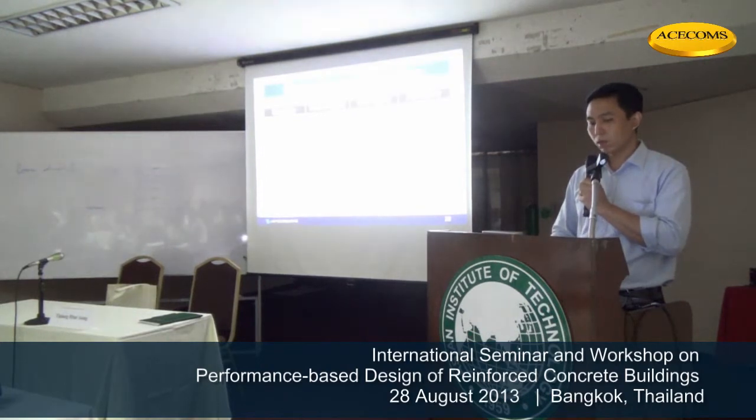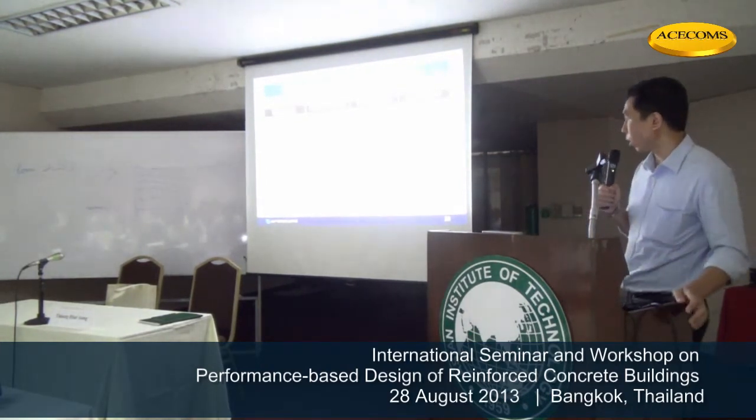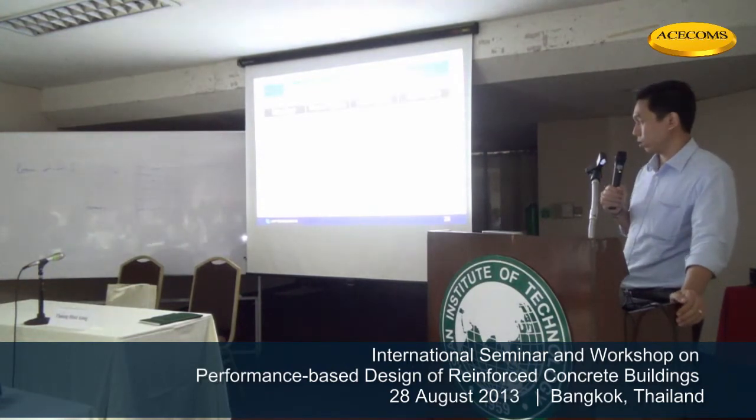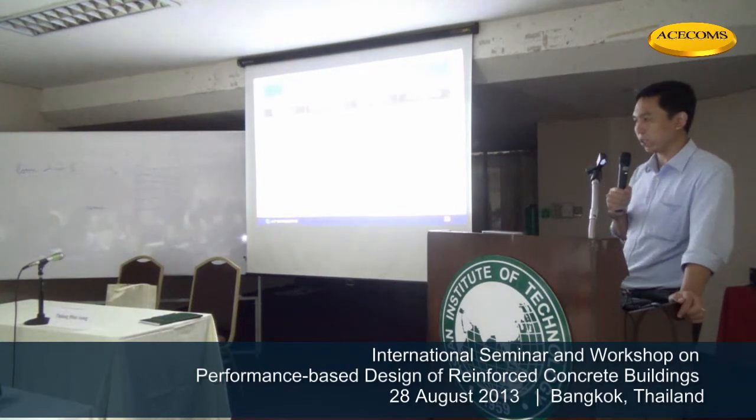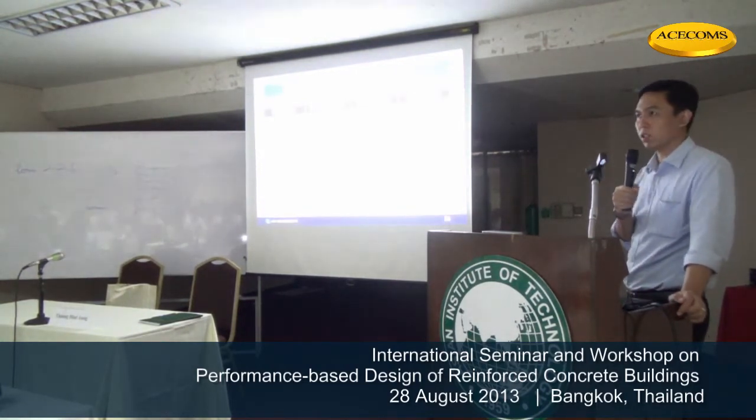So to get serviceable under the frequent earthquake, we use the service level response spectrum to check the building. For the service level earthquake, we want the building to remain elastic. We do not scale down the base shear for the service level response spectrum analysis. We just do the elastic analysis using the service level response spectrum.